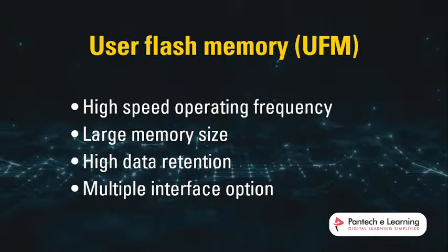Multiple interface operation means you can access it remotely. Our FPGA has the RSU, remote system upgrade. The remote system upgrade is based on UFM memory only. There is separate code in the IP for the RSU. You access the remote access by using the UFM memory only.